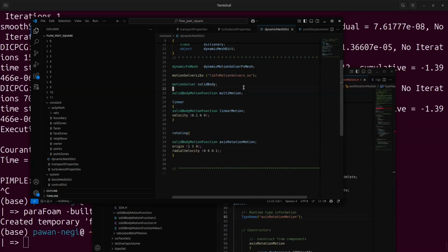We are on a single mesh, we are trying to move a patch or the entire mesh, and whenever we are moving the entire mesh, this can be used in flows. For example, in tank sloshing, we are going to move the entire domain with some acceleration and then suddenly stop it. We can do these kinds of things using this particular mesh motion.